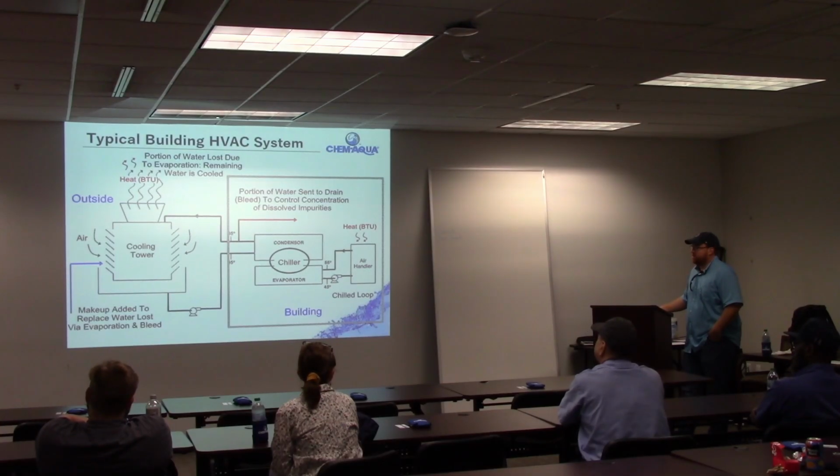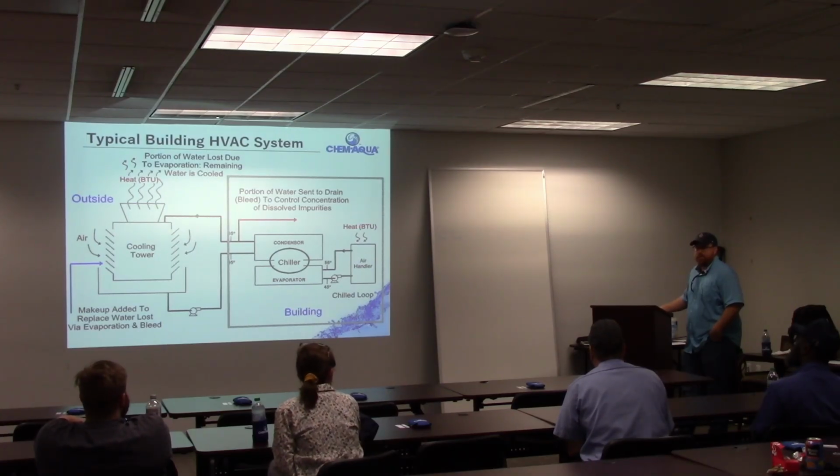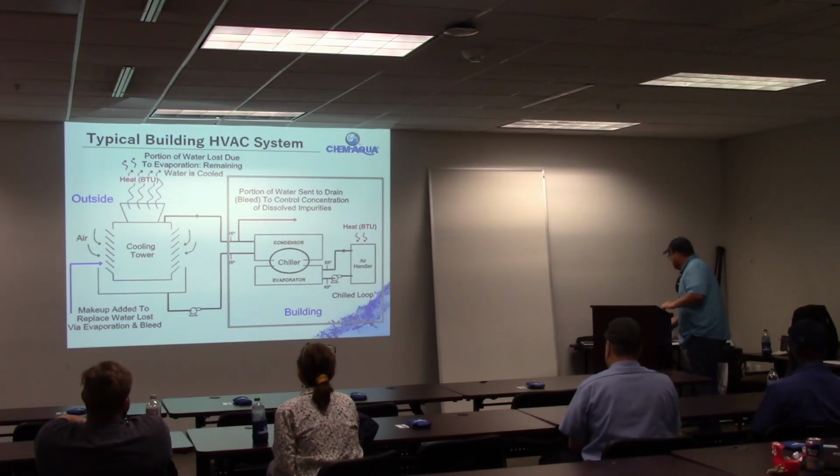The Cooling Tower Institute recommends tower cleaning at a minimum once a year. A lot of people don't want to spend money on cleaning the cooling tower, but that extra 1 or 2 degrees of temperature split can make all the difference in the world. Over a period of a year, the energy savings are probably going to pay for the cooling tower cleaning.